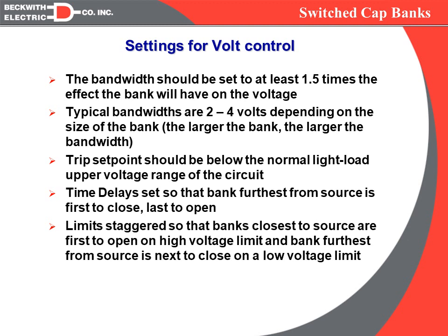We should also make sure that our voltage levels are set to trip at the lightly loaded time of the day, whatever that voltage is when it's lightly loaded. Because if we don't, the bank will never operate. So if we set our open voltage higher than the lowest voltage it's ever going to see, then we're never going to have a bank close or open. So we've got to look at our voltages at full load, what's the voltage we anticipate, and at light load, what's the voltage we anticipate at the location of the bank, and make sure we keep that coordinated.